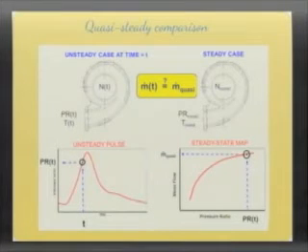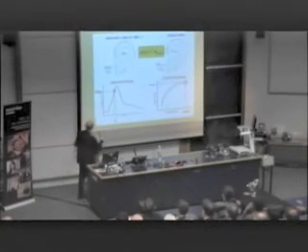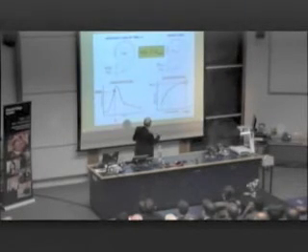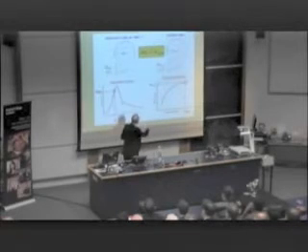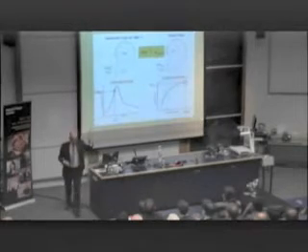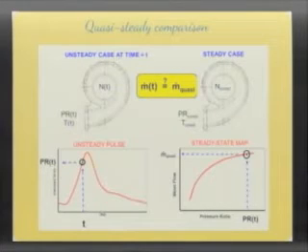Is my machine near steady state? Can I consider the design of my turbine in a steady state fashion, and therefore say, from a pulse generated in a machine like that, I take that time, I read that pressure, I go to the map that the manufacturer has given me, acquired in steady state, and I get that pressure and I read the mass flow? How much air my engine is swallowing, how much pressure the turbocharger sees. And I say, this guy's given me the map in steady state, no change in conditions, no fluctuation change, I should say. So is that the case?